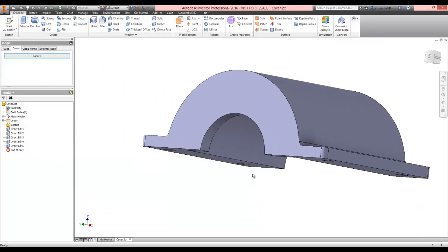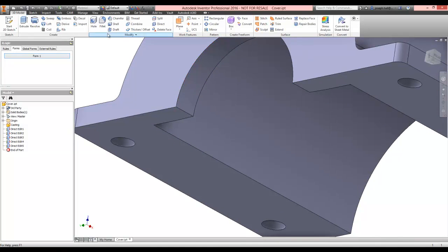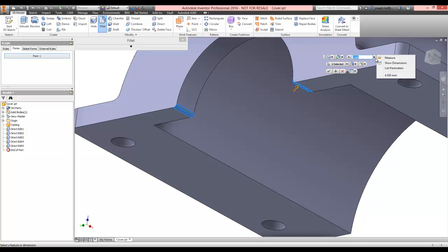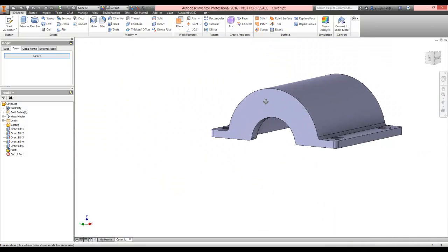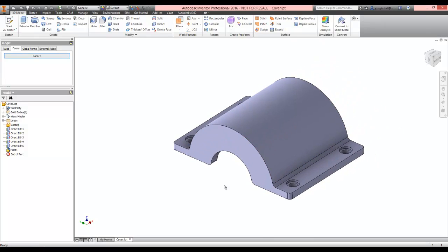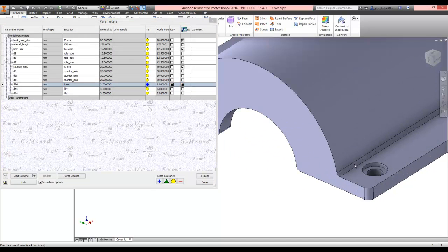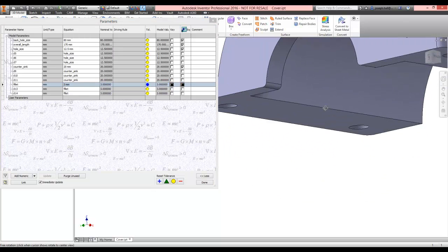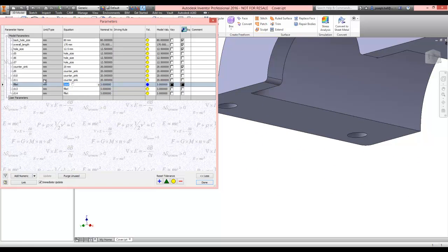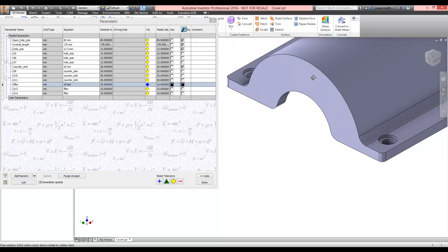Nice and straightforward. And the other thing to do with that is if I were to put a fillet on the inside of these two models, I could now say, list me the parameters, that's the same size as fillet. So now I've added a whole new level of intelligence to this, whereby this was direct editing. Now the fillet parameter here, I could change that to say 3mm. It's not only changing my direct editing geometry, but it's also changing my model geometry. So if that goes back up to say 10, you can see that's going to have an impact on what we get on the screen.